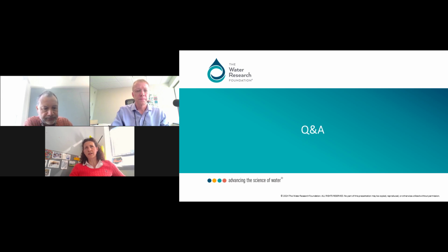So the question of SRT remains: what adjustments are needed at low temperatures? At Pomona, we'll talk about that more in this third webcast. But at Pomona, we were very intentional to not change the SRT and we didn't change the HRT. We didn't lower the load coming into the facility.